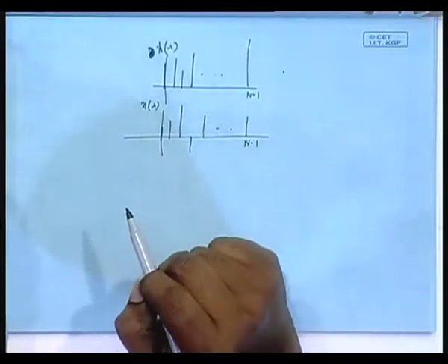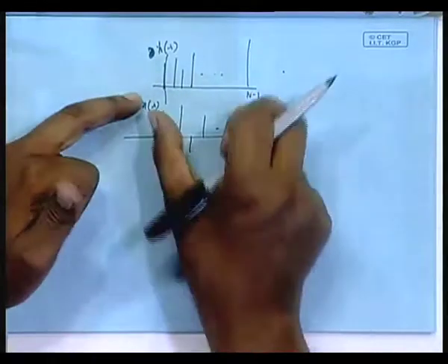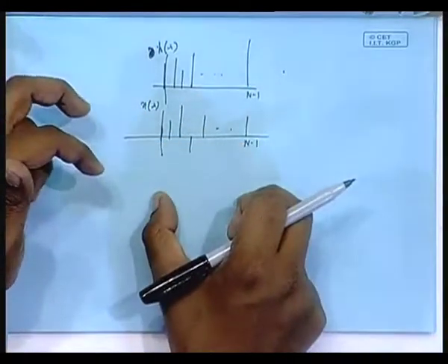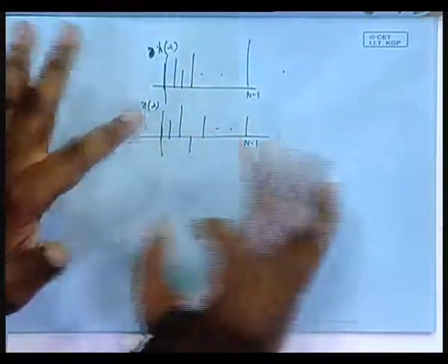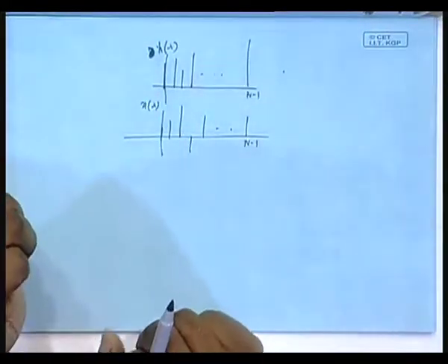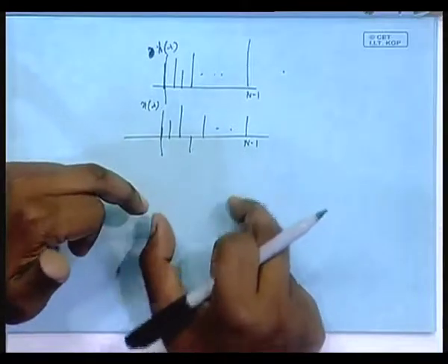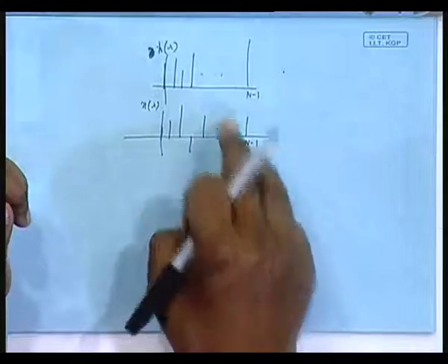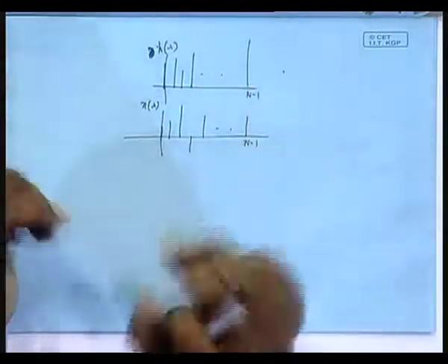Before you do the circular convolution, what is circular convolution? Actually, you are doing N-point DFT, multiplying, inverse DFT. You will get an N-point sequence. What is that? That is not linear convolution, it is a kind of complicated thing which you evaluated. How to get that graphically, that is what you are asking. That sequence is called the circular convolution output, or periodic convolution output, obtained by periodic convolution between the two, or circular convolution between the two.